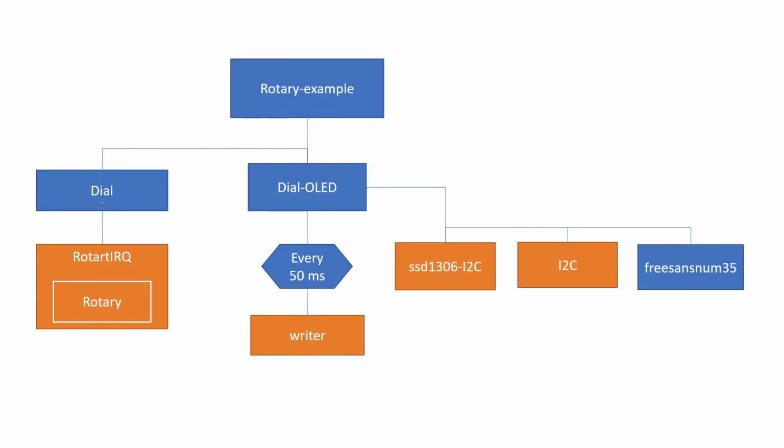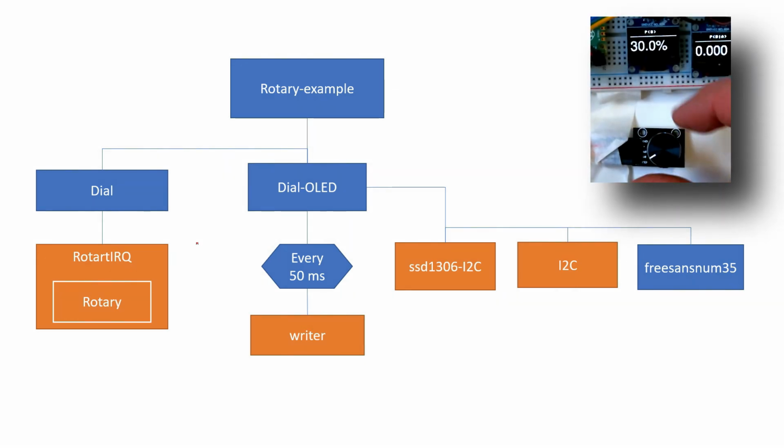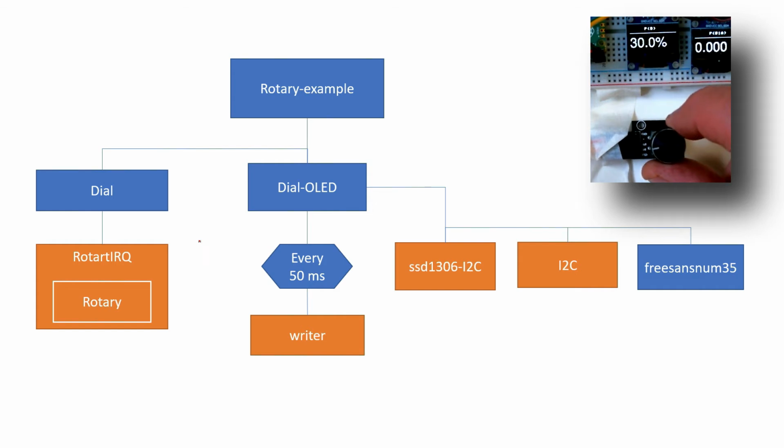But basically the idea is I've got a couple of classes, this dial class, which controls the rotary encoder. So it does things like being able to set the increment, being able to press the button on the rotary encoder so it changes from incrementing by hundreds, tens or ones, so a quick way of setting the value.